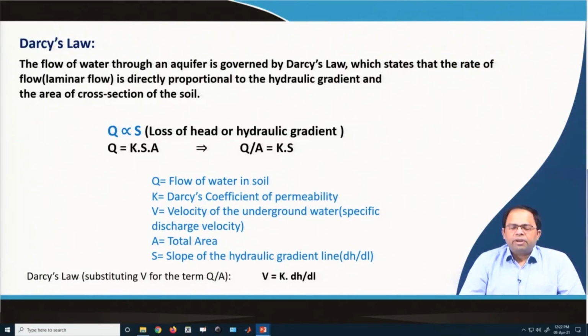So, that means when we talked about hydraulic gradient, it was the change in the height, and we have also talked about permeability, which was for unit area. So, when we want to decide for a particular well, the well has a larger surface, so we have to multiply with the overall area for this particular value.